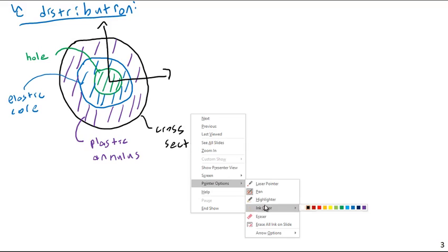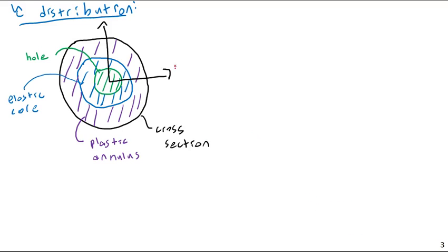Now, let's see here. Very similar to the strain, the stress would start at 0 at the center. However, I have a hole here, so I'm not going to have to worry about that. It would go to 0 if this were solid, but because there's a hole here, the stress is simply going to increase as a line from the center, in a linear relationship that would go to 0 at the center.